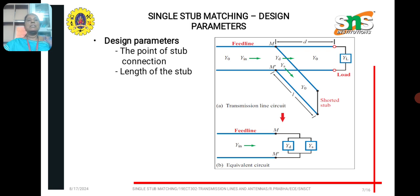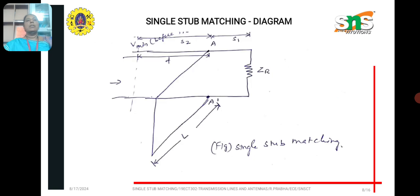There are two design parameters in single stub matching. One is the point of stub connection, that is, the distance from the load side where the stub is connected across the transmission line. The next one is the length of the stub. These are the two important design parameters of single stub matching. Consider a diagram where the input impedance is Z0 and the load impedance is R0.